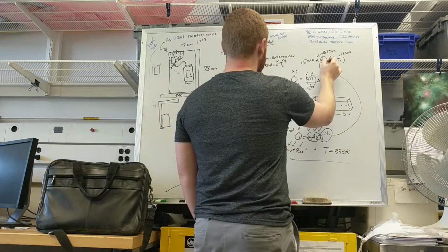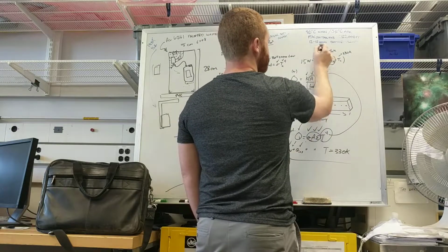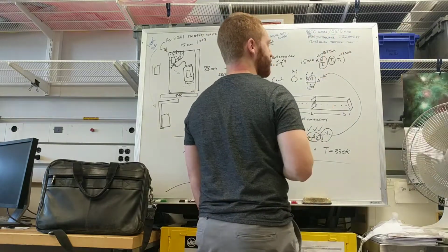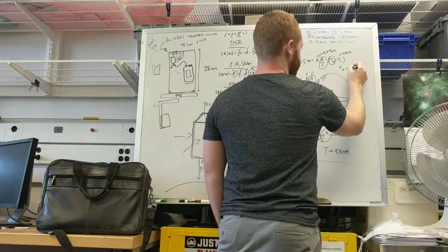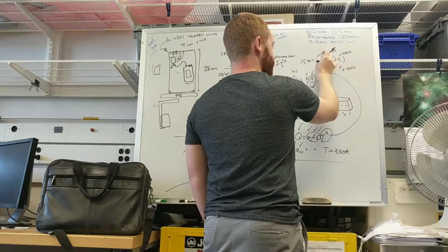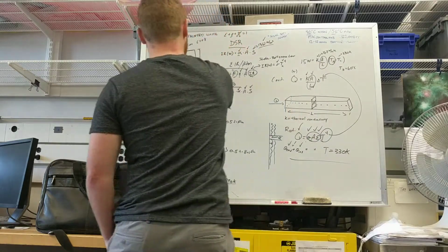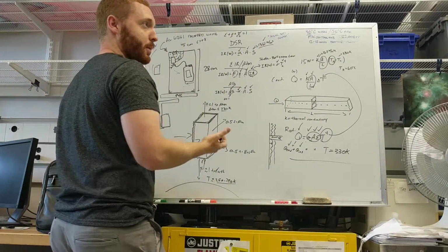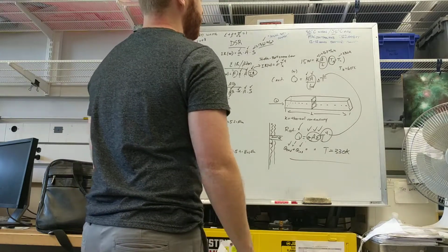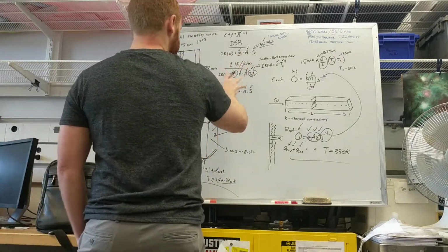Then you compare that TH to your 40 and your 50, and you see where those are. If your TH comes out to be 60 degrees C, then you have to either make the cross-sectional area of the bar larger or the path length shorter, or both. But that's how you take into account these environmental loads.